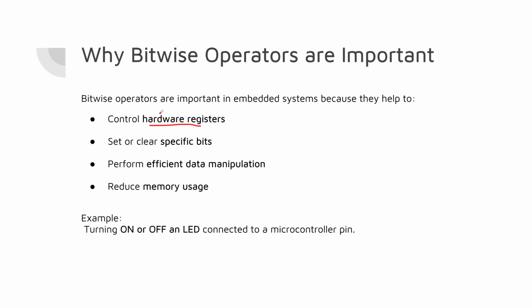Similarly, all the hardware register control can be done by using bitwise operators. Like if I want to make a bit 0 or I want to make a bit 1, everything can be done using bitwise operators. As well, by using bitwise operators, they say that it is efficient data manipulation. Also, memory usage is low when compared to some other methods.